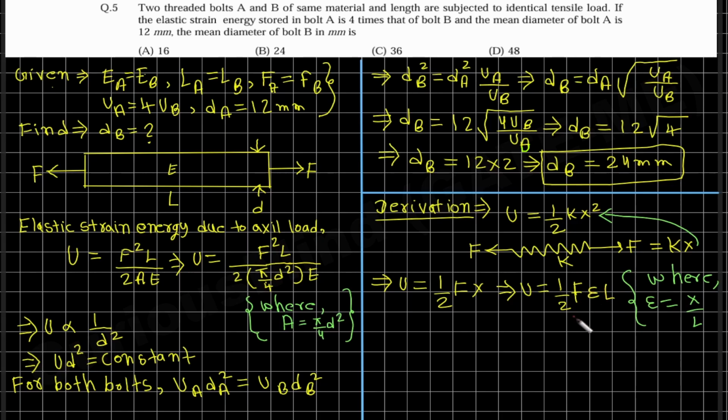Now we further have to eliminate this epsilon, which represents the linear strain. For this we use the stress-strain relation for the axially loaded bar, from Hooke's law, because Hooke's law is applied for elastic material. For a linearly elastic material such as this bar, the stress induced in it due to the applied force F is proportional to strain.